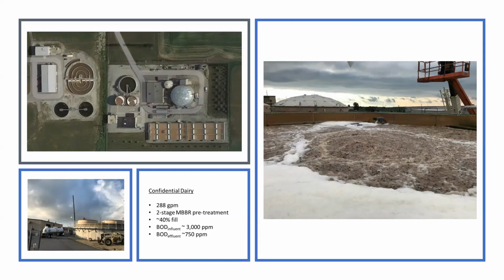In this case, what they did was build what they call a calamity tank. It's a fairly unique process, very sophisticated even. They placed a COD analyzer in the raw influent stream to the wastewater plant, and anytime the COD value registered above, I believe it was 8,000 COD, they would divert the flow to a calamity tank until the COD value decreased. Once that COD value decreased, the wastewater would proceed to the wastewater treatment plant as normal.